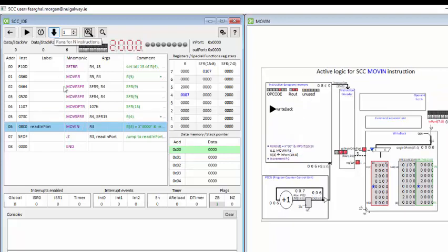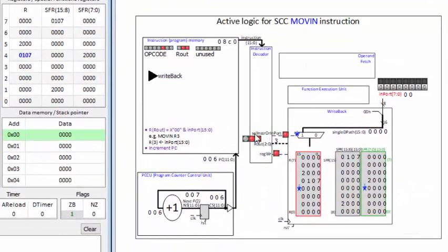And single step again. Now there's an instruction called move in, which takes the import, which is 8 bits, and pushes it through this multiplexer, which is controlled by a signal called select instruction or import. It's related to the move data pointer. It uses some of that hardware, and it's taking this value through to write to the register bank. I can read the import and write it to the register bank. Reg write is asserted as before. The destination register address is 3. It's in the instruction as before, and a new opcode. This is writing to register 3 here, and the program counter is incrementing again.